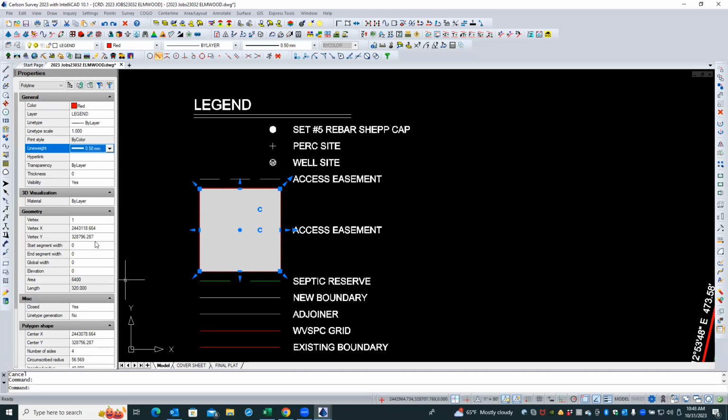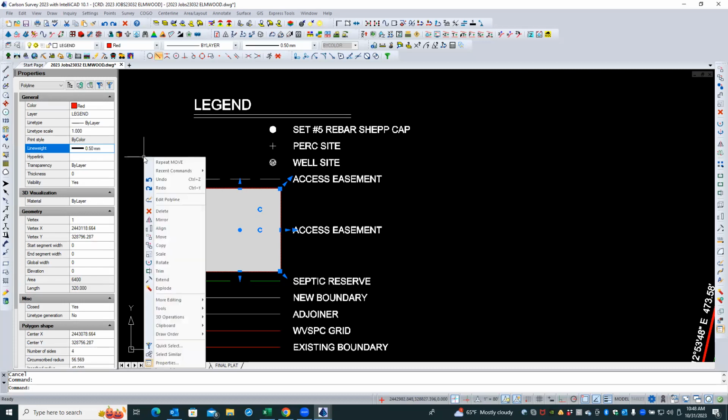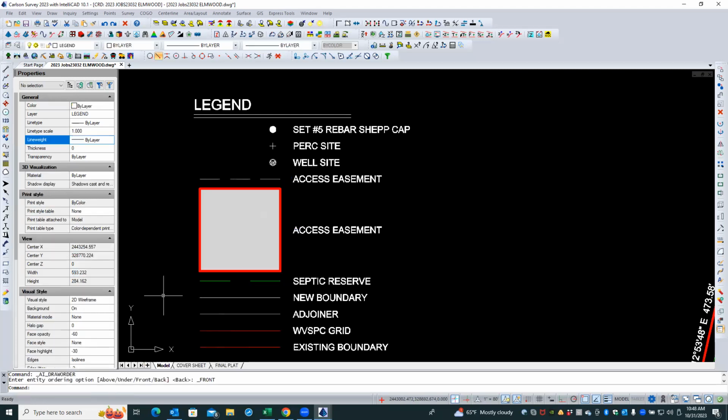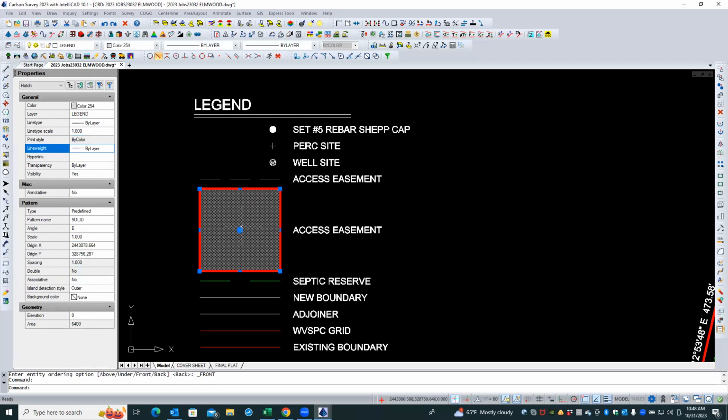And now over in the drawing, right click and choose draw order, and bring it to the front. Okay. Now, we're going to just keep that there so we can be reminded that we have it. Otherwise, it's the same color as the hatch and we'll forget about seeing it. Now, let's click in the gray part of the hatch so that we select it. And we're going to slide the bottom grip right there. We're going to click that and go upward and push it up, and you can hold the shift key down just like you did on the move.